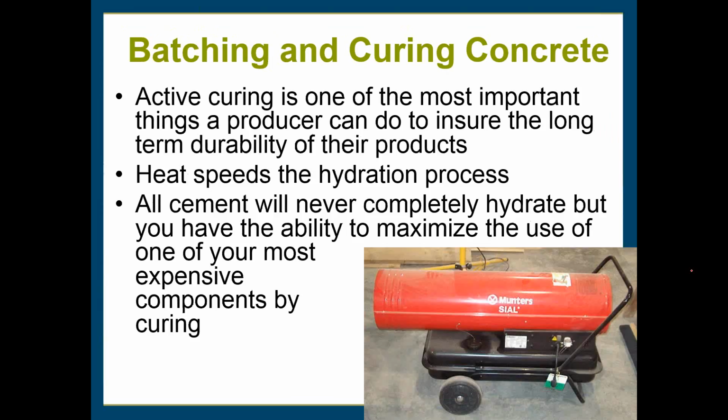heat speeds up the hydration process. How many of you use these heaters and tarp your products to keep the moisture in, keep the temperature at the appropriate level when you're curing? Does anybody use anything like this? One person said yes? Okay.